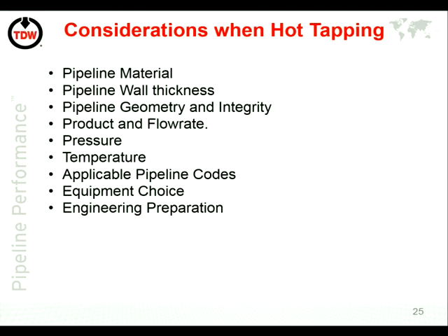There is a limit, and it will vary with pipeline diameter, but there is a limit as to how much flow you can have when you drill into a pipe. And obviously pressure as well. We mentioned the limitations on pressure because there are a lot of pipelines which are higher pressure than that. And again, temperature comes into it. And also, this is more for the purchase of the fitting itself. You've got to know what the applicable pipeline codes are for that pipeline, and they can vary around the world.